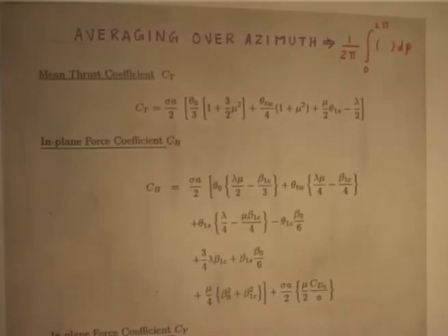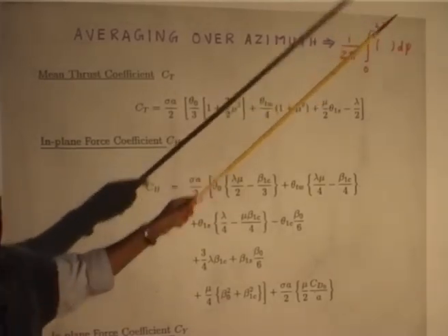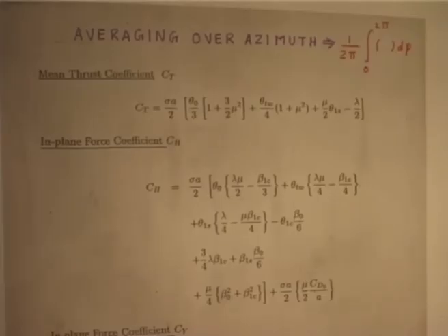That means what is my thrust value? You have to take only the mean value. What is my longitudinal force? The mean value of the longitudinal force. So, that is why when we get these loads, we take average values. The average is done by summing over all the blades, then integrating over one revolution as the loads change, and taking the mean value, and the mean value is the same for all the blades.